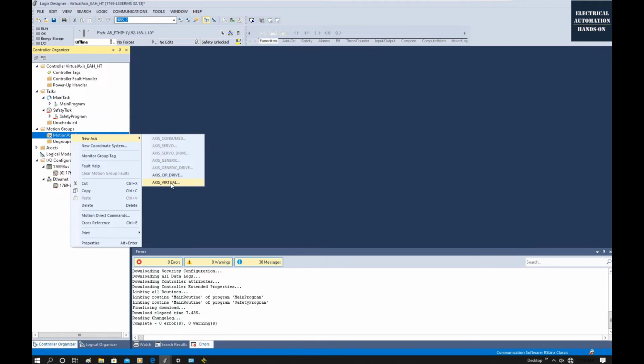So using the axis virtual is a similar idea to how we set up a virtual axis using the TO technology object in the Siemens TIA Portal software. Based on this virtual axis, we can test the motion instructions, for example, halt, jog, or move, or do some speed control. We can test our logic only. We do not need to wait for our actual servo hardware. Especially for the new learner, you do not need any motion hardware, so you can do this test.